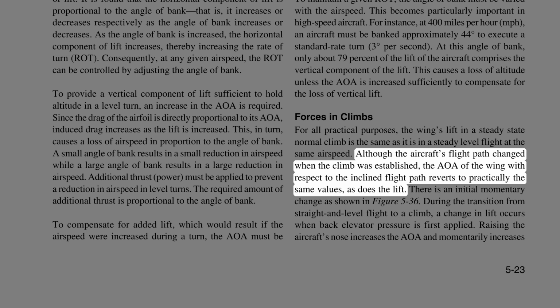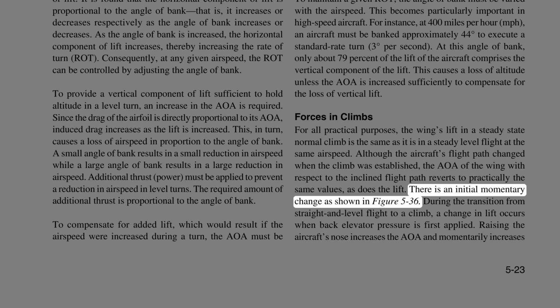Although the aircraft's flight path changed when the climb was established, the AOA of the wing with respect to the inclined flight path reverts to practically the same values, as does the lift. There is an initial momentary change as shown in Figure 5-36.